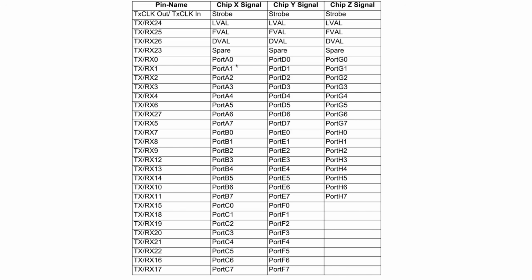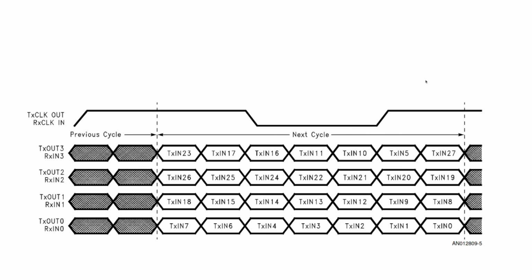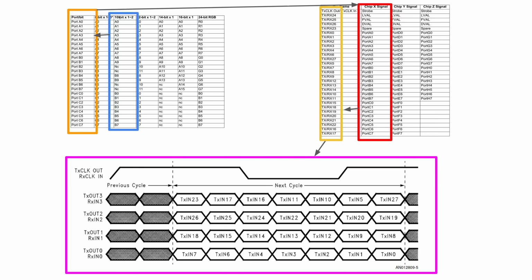Okay. Now we take that port number. So we have these A0s, and then they go over here. So this is the specific bit position in the sequence over the 4 lines. So B1 goes to RX8, A0 goes to RX0. Now this is the actual bit sequence in one clock of data. All right. So every clocked piece of data will send out this specific sequence of values. So now what we have to do is we take this chart, we map this over to the ports, which maps over to the RX signals, which gets sent out to here.